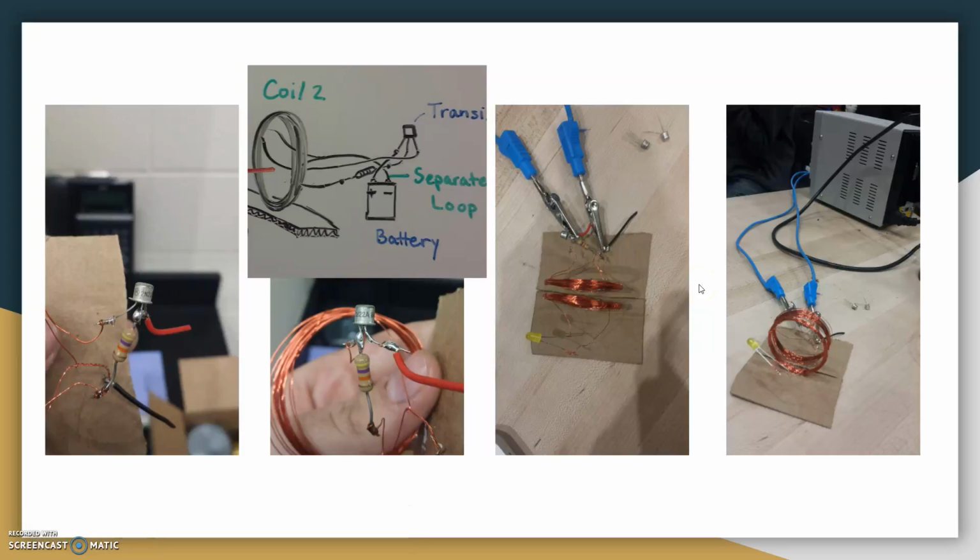Since it did not work with the battery on our first try, we tried hooking up the two free ends of the transmitting coil and taking out the transistor, as seen in the last photo, but this did not work either. One problem we had was that there was not a good enough connection between the soldered copper wire and the ends of the transistor and resistor. We solved this problem by burning off the copper enamel instead of scraping it off the ends of the wire.